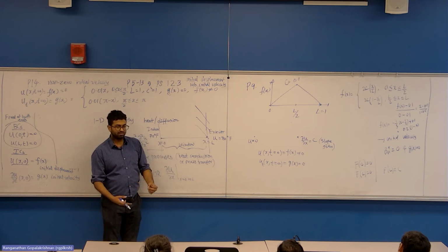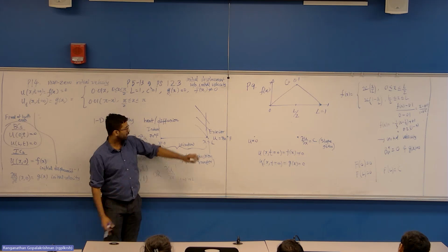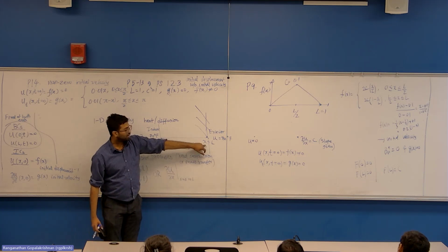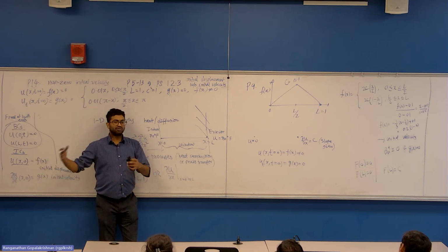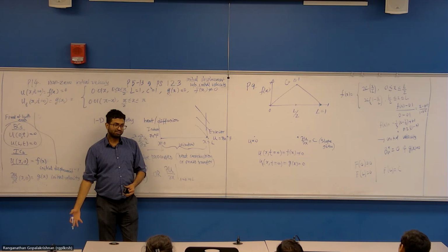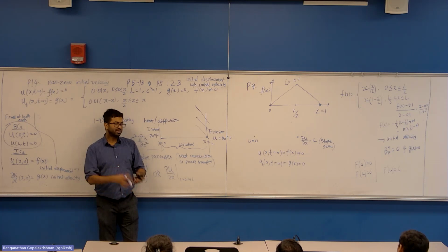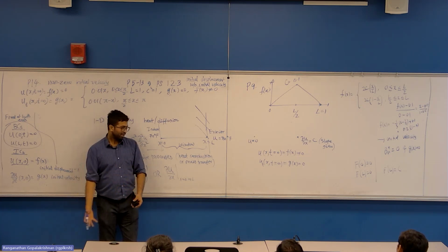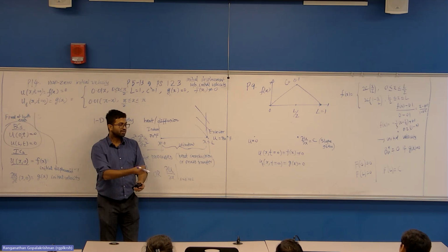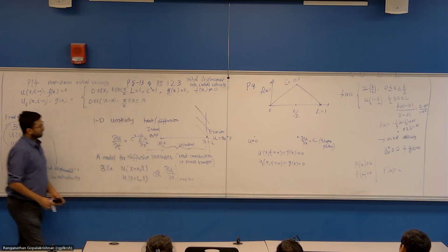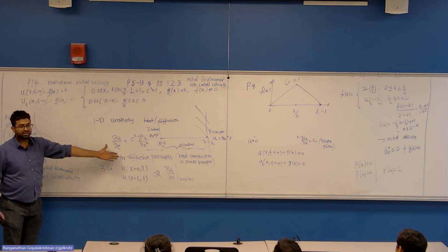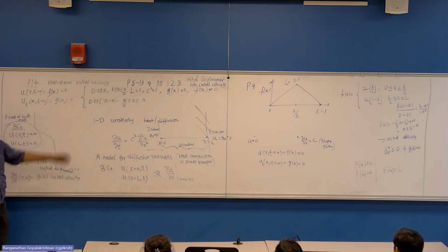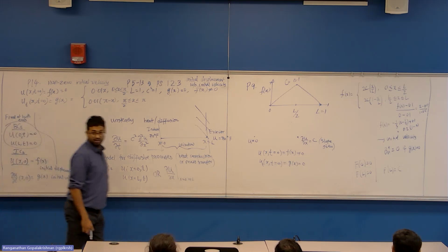This is a very minor nuance that you have to notice, that you have to compute the value of U here. Suppose one of your problems could be, if a heat flux is maintained at one of the walls, find the resulting temperature. So you'll have to get the solution and substitute x equal to L in order to get that temperature. It's like one step extra. All right, good. Can you tell me what to do next? Like separation of variables, the same procedure can be applied again.